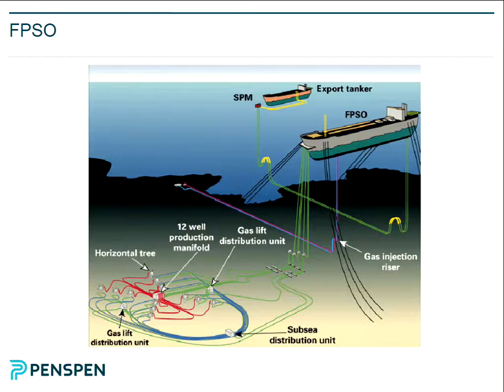An important thing about an FPSO is the turret. It's not particularly an issue for multi-phase flow, but basically you get the point that's fixed with anchor chains on it, and all the risers connecting to it, and the FPSO moves around it, and then you connect the process equipment on the FPSO to the risers through what they call a swivel.